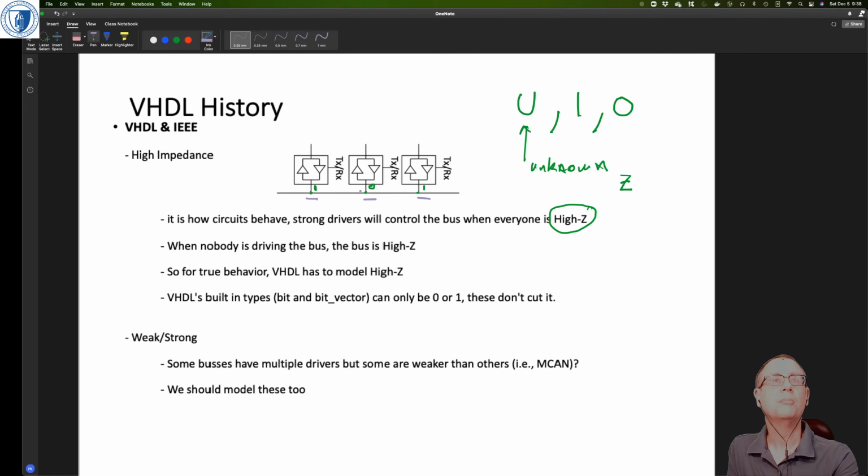If you've got both of those on, then the value here is not determined. If you've got both of those on as an output, again it's undetermined. It's not quite the right thing to do to have two outputs driving the bus at the same time. Got it. Okay. Sorry about that.